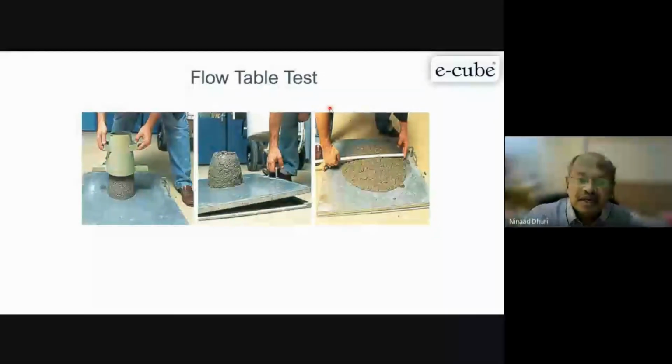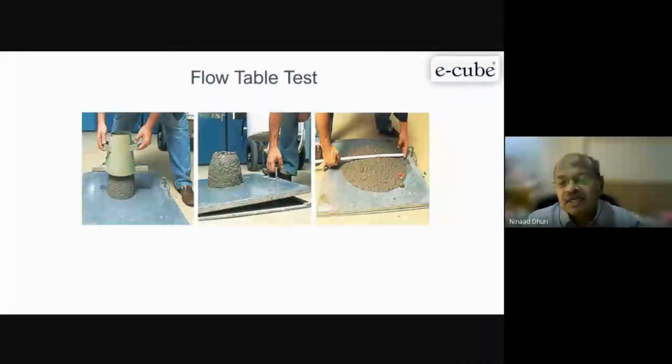Now once the concrete is totally flowing, slump test is not applicable. We have to go for the flow table test. Now that concrete you are already vibrating, so that's why this lifting arrangement has been given, to simulate the vibration effect. And even after 15 drops, if we say there is no segregation, no cement separation, this is a good concrete. That one has to understand accordingly.